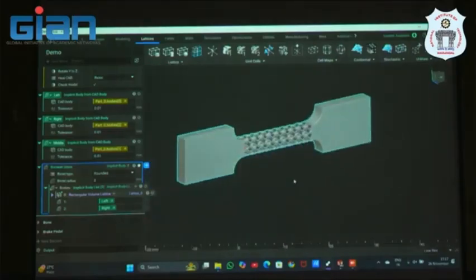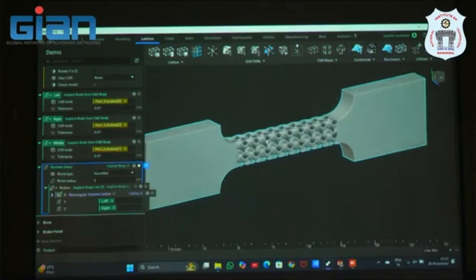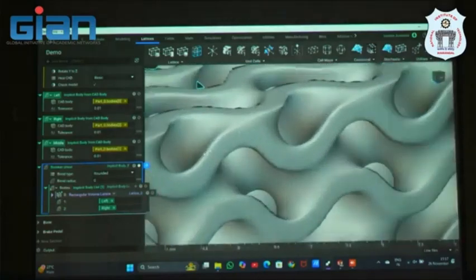So we can mesh the 3D body. Why STL? This has intricate geometries, right? See, if I want to capture this sharp curvature of geometry, I need to use tessellations only. Some solid bodies, original bodies, we can capture in the IGES or STEP format. But to capture very intricate, precise geometries, we use tessellations only. Okay? Why tessellation? Why triangle? Why not square or something? Why can't we capture with the square? Why triangle? Why is STL called a tessellation?